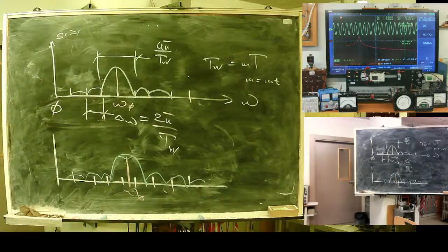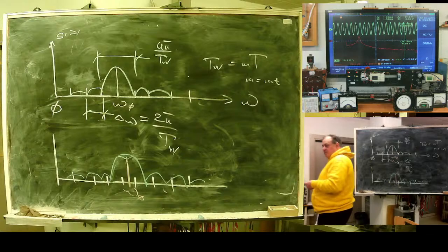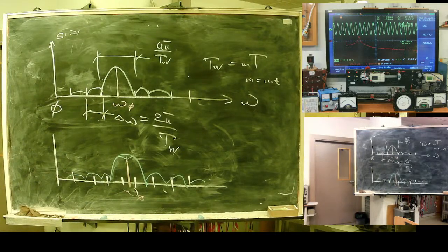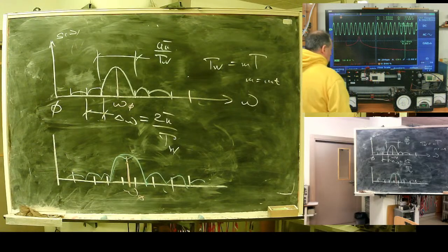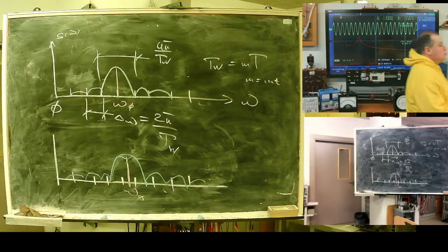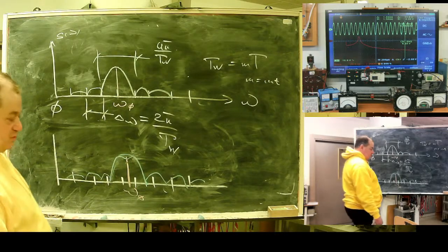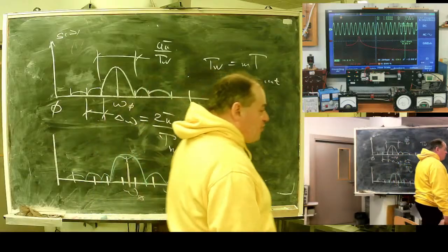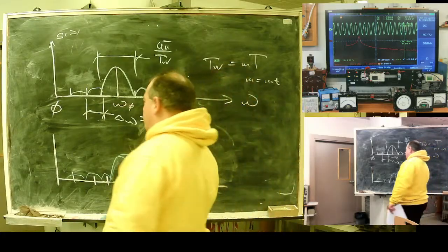If we would like to have less distortion from the windowing function, we can manipulate it. We can use a specially crafted windowing function with the aim to reduce or diminish the effects, where the effect comes mostly from the sharp change at the beginning and at the end of the window function.